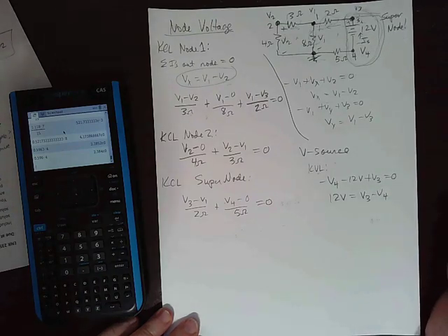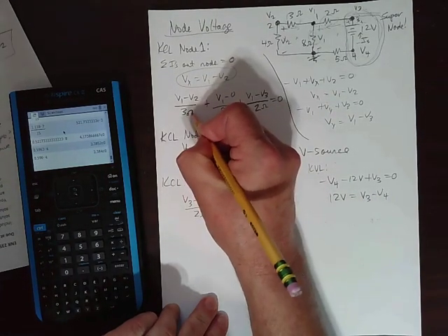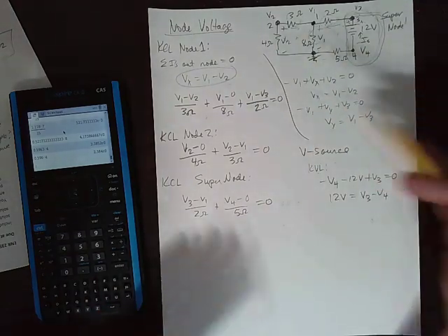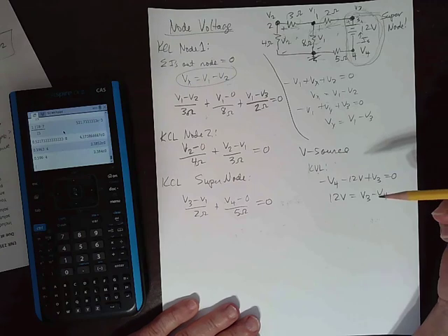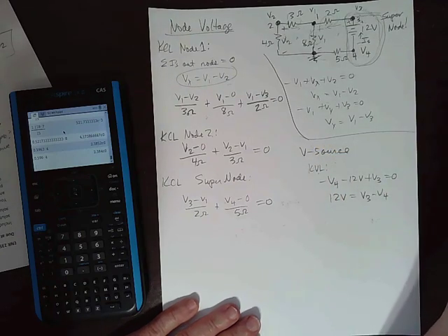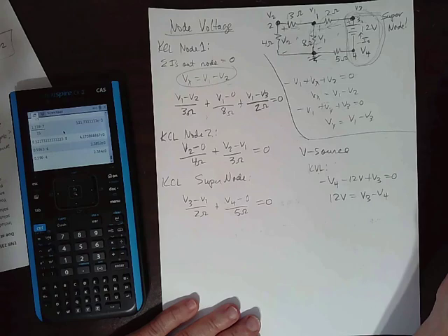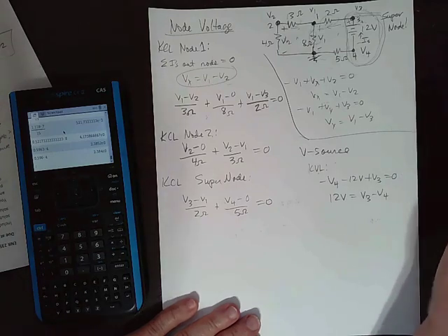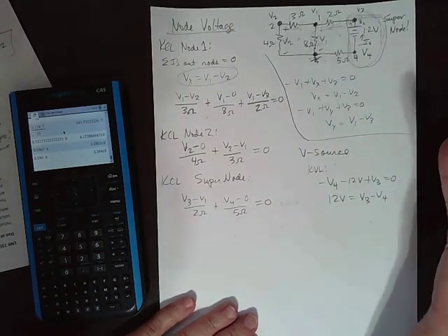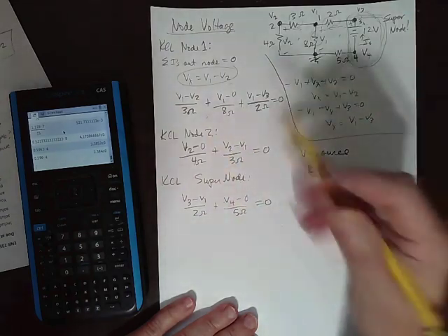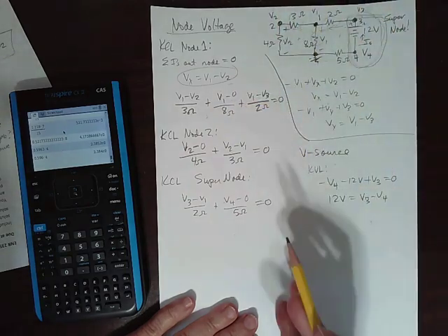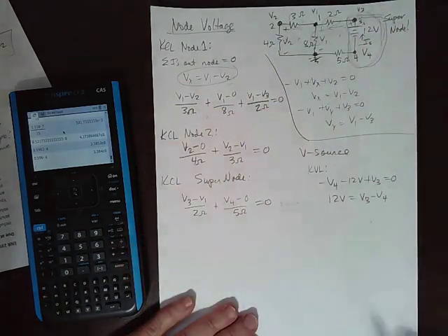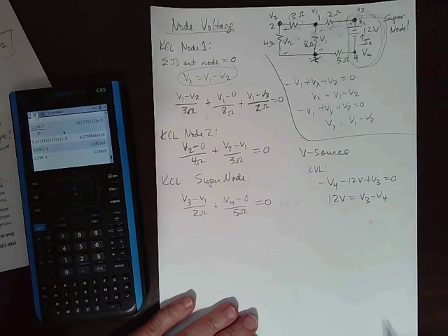So how do we want to solve these? This is a general method, right? You go through the process, and you can maybe get a mess of algebra. That's why we use matrix theory and have the computer do the calculations for us lots of times when we have large circuits. You can get power system circuits or different kinds of circuits with 1,000 nodes or more, and you have this huge matrix, and we can write these equations as coefficients and then a vector of voltages, and use matrix math to find the solution for us.